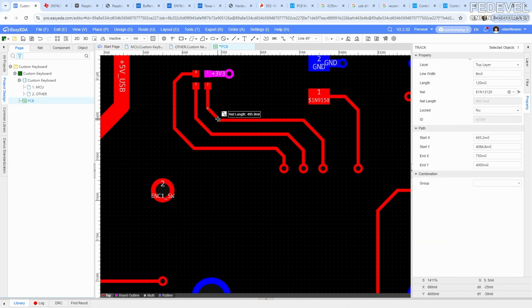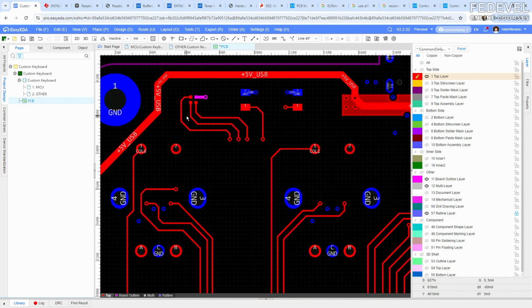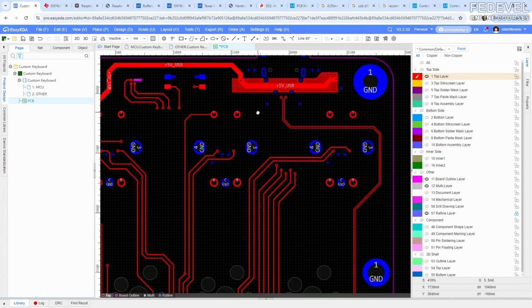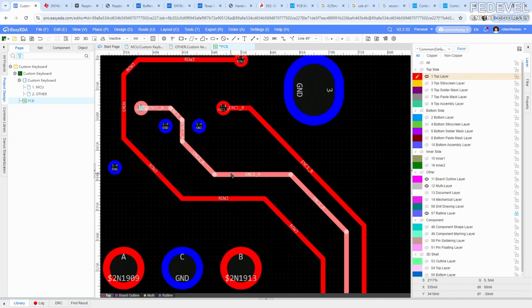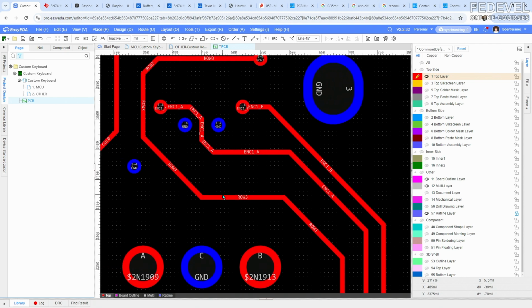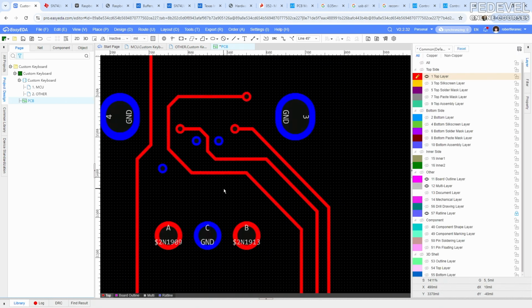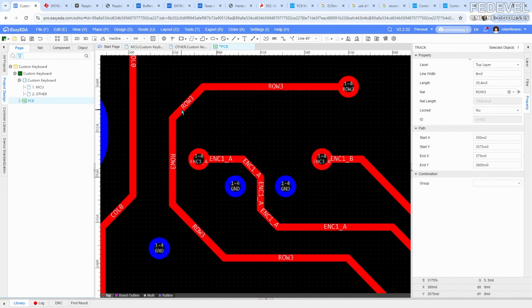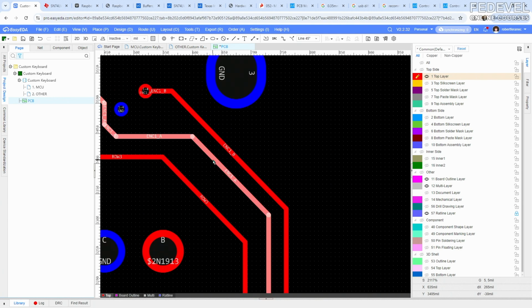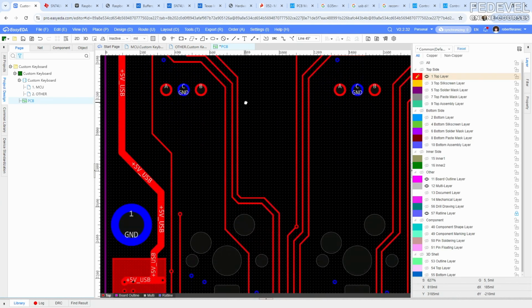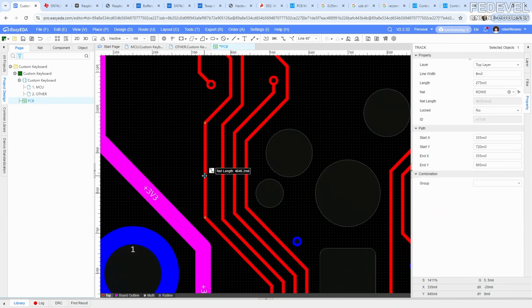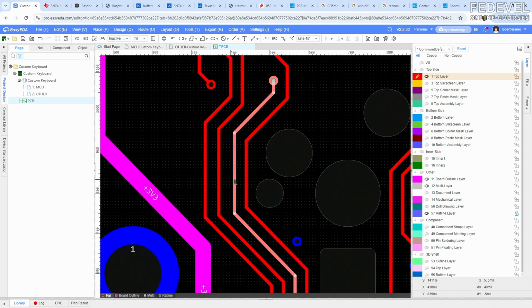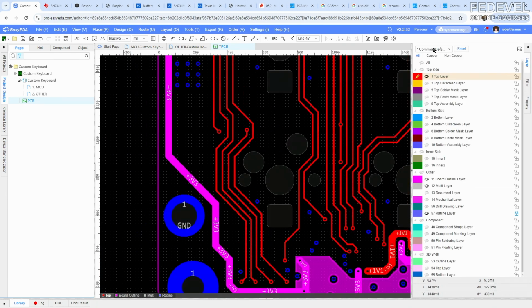This is really a visual thing. Because this is a top layer, everyone will see this top layer, so I try to make it as nice as possible. These small changes, what I'm doing right now, are not really going to influence anything electrical on the board. But still keep all the tracks away from each other. Like here, I'm going to move it a little bit because of crosstalk. If we have a lot of space, we don't need to route them very close to each other.